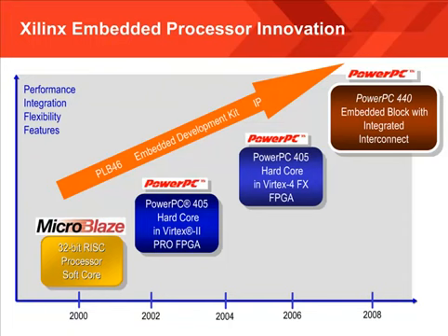Both of these processors use the PLB v46 bus standard, and EDK includes IP that is optimized for this bus standard. This means that any IP that is optimized for the PowerPC 440 can be used on a MicroBlaze system and vice versa. Xilinx also provides a PowerPC 405 processor core in the Virtex 4 FX product family. This processor uses a different bus standard than the MicroBlaze or the PowerPC 440 cores.